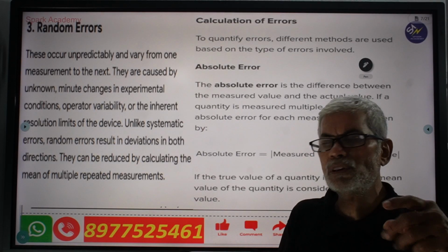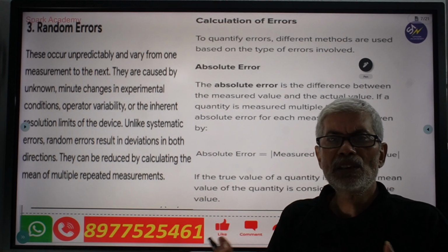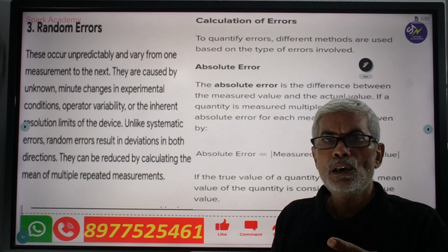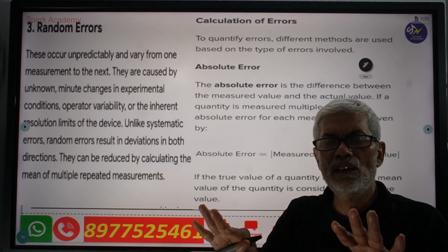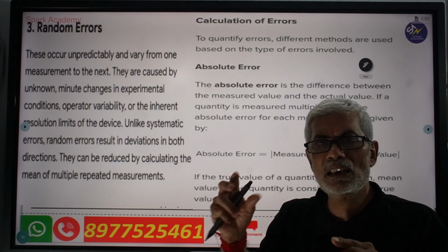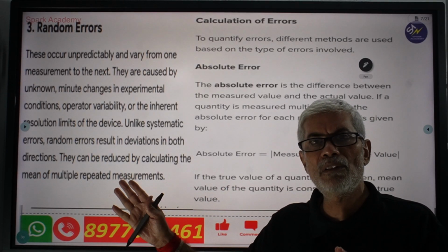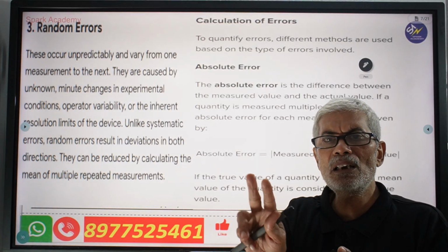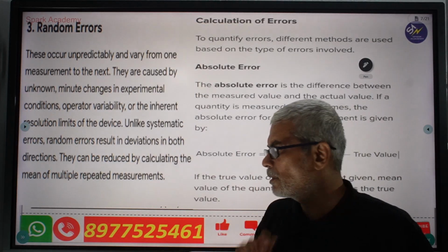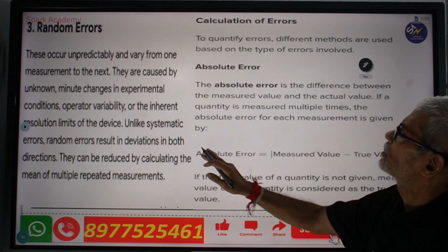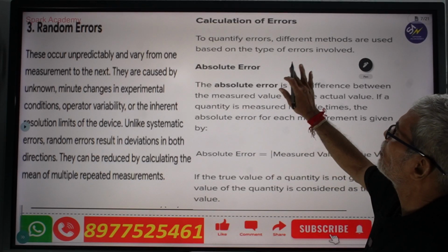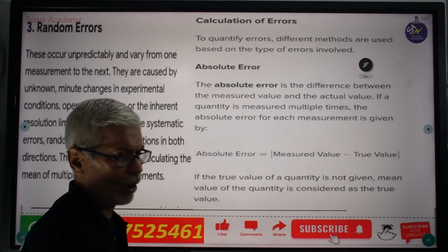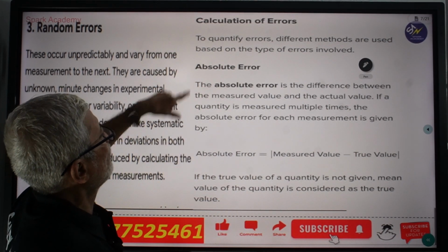And then suppose a crosswire is given, and they ask what is the distance between two vertical crosswires or two horizontal ones. The crosswire will have both horizontal and vertical wires, no? So you have to adjust the instrument in such a manner that all the vertical crosswires vanish and only horizontal ones are seen, and vice versa. So that very accurately you can find out the distance between two wires. Now there are some calculation formulas, and then we'll solve some problems.